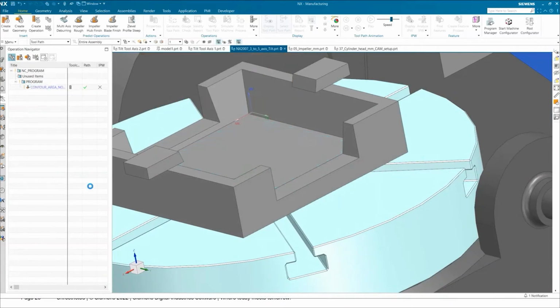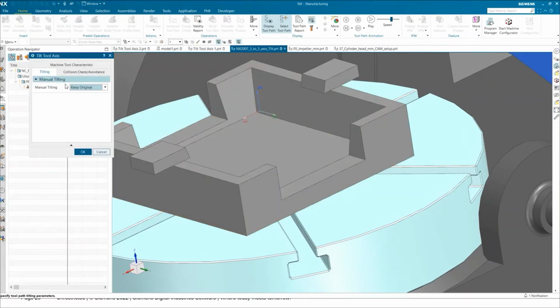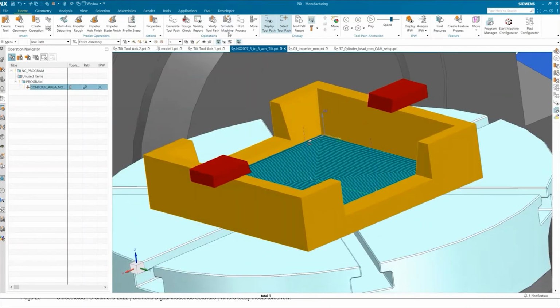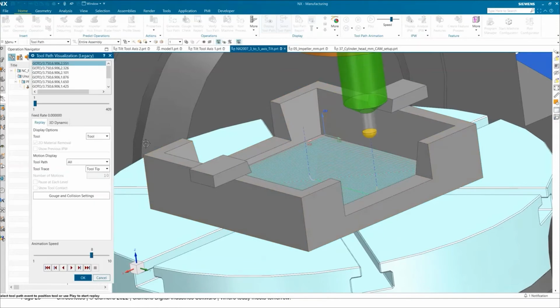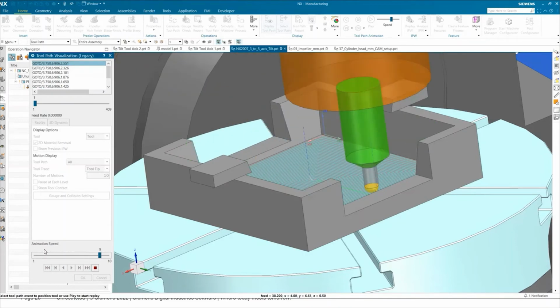So what we'll do is same thing I just did. Go over here, toolpath, tilt. Fairly quickly, I've tilted this toolpath. Now I can come into my verify. And if you say play, you'll notice that it's tilting and I am now not colliding anywhere on the path. So that's it for the tilt tool axis. Very handy